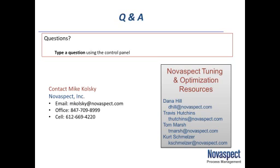One thing I'd like to point out is people very often say the cascade slave needs to be tuned 5 times faster than the cascade master. The Lambda method gives us an objective method for how to do that. That simply means the cascade slave has a lambda time 1/5 of the cascade master.